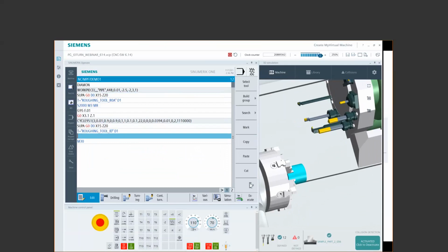We can reissue our spindle speed. I'm just going to stay in straight RPM for this example. Certainly you guys could get into G96. I've shown you all that good stuff in previous webinars. I like to certainly repeat some of these M codes. This way, if I mid-program start, I don't have to worry about the scan being on. I am a big advocate of reissuing my G95, although it's not required by any means. Maybe I'll run 20 thou per rev.